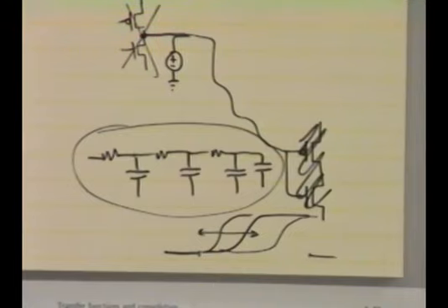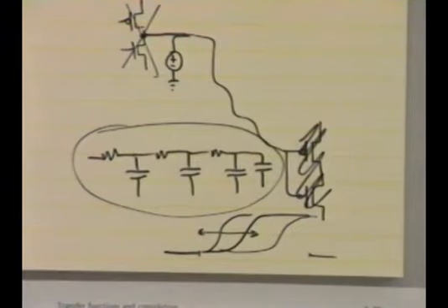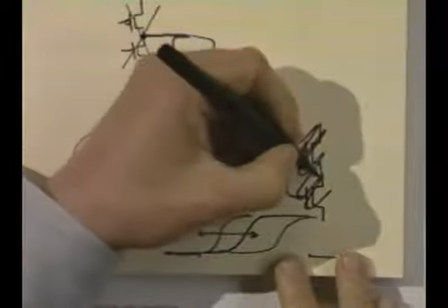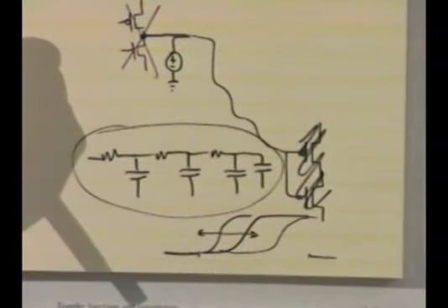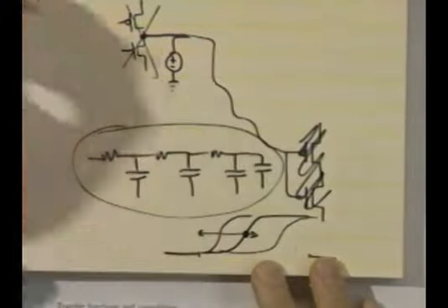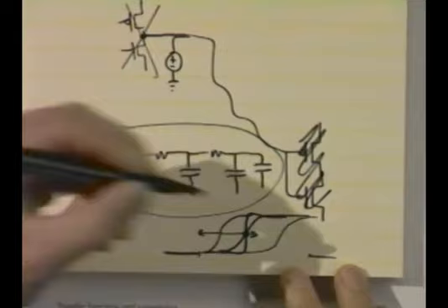So that's it. Step response comes up throughout. It basically dominates much of the design at the transistor level of digital circuits. That's how it works. And the step response means everything. If this gate is set to flip when the threshold is a half, then you're looking for the point at which the step response reaches the critical value 1/2, because then the output would look like this, right?